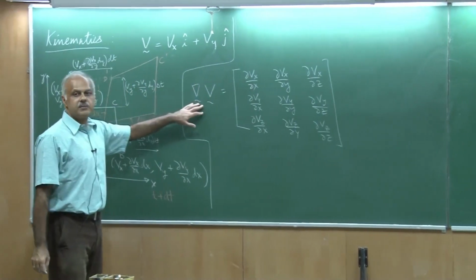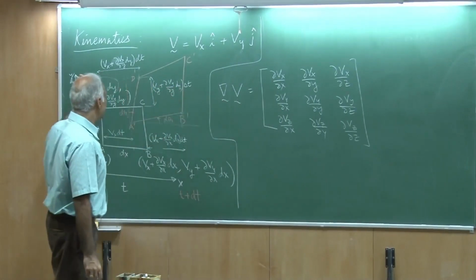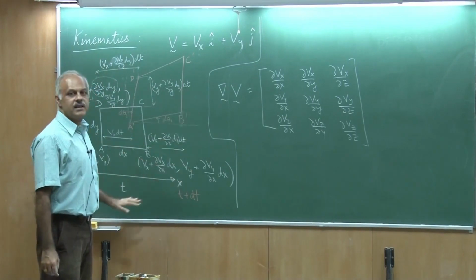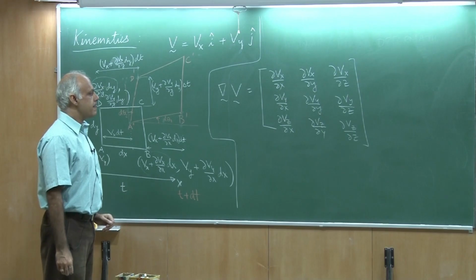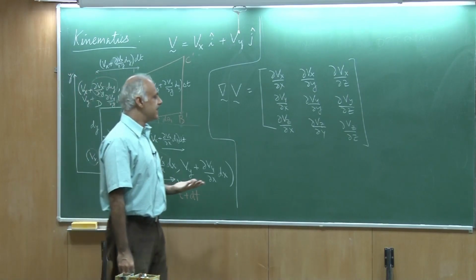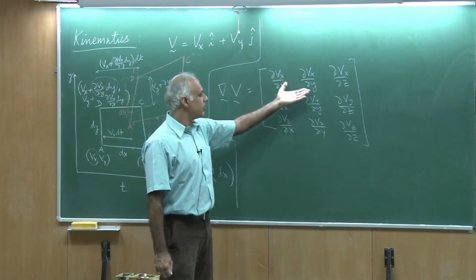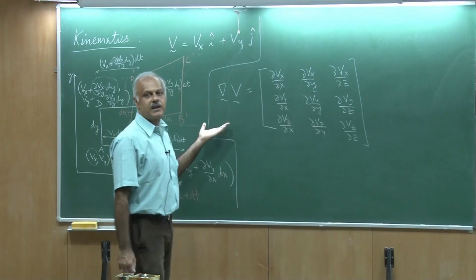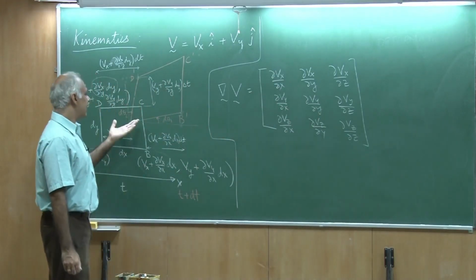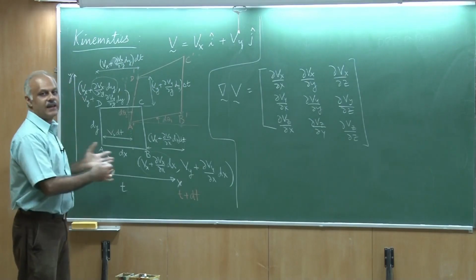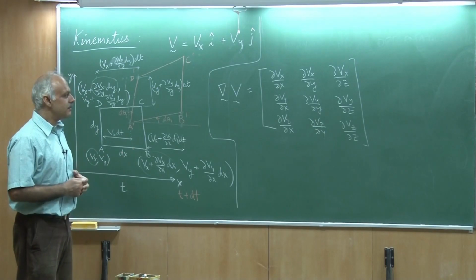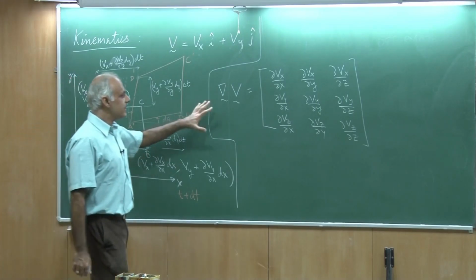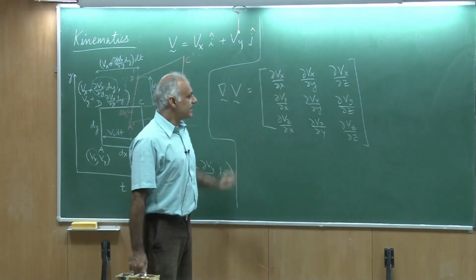And this is arising because the velocity field that I have in this 3-dimensional space is changing with x, y and z. Okay. If it is a uniform flow, then you would see that this gradient of V becomes 0, and then of course, these elements would simply translate and not deform or rotate or do anything. So, that is a very bland kind of a flow, not very interesting. But if the gradient of V is non-zero, then I get a scenario like this.